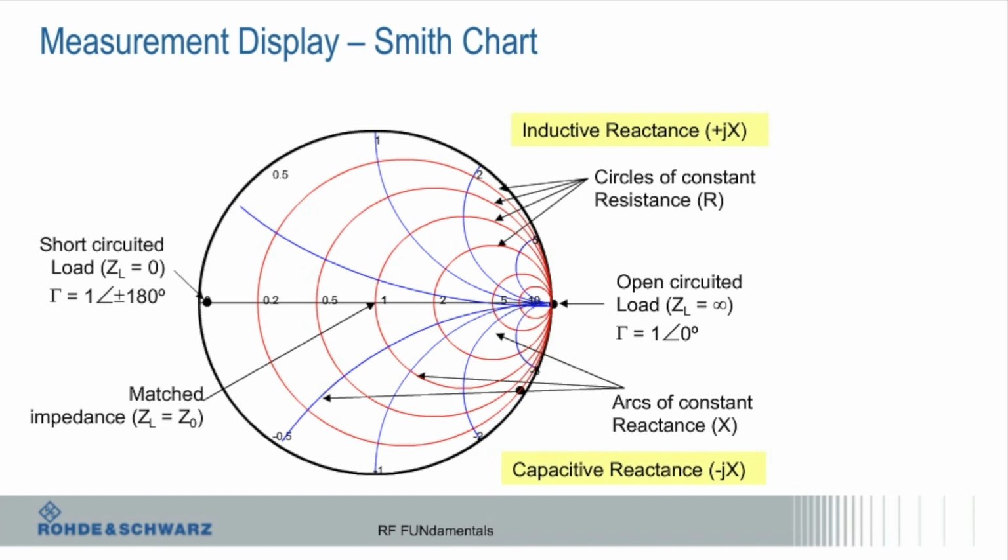So you make it something close to that, and then you measure the hell out of it, right? And you get some really accurate data. So when you send in your cal kit to get it calibrated, they're really, really accurately measuring what that thing is over frequency. So when you do the calibration, it isn't that it says, oh, that's a perfect short, and I get a reflection coefficient of 1 and a phase of 180 from DC to daylight.